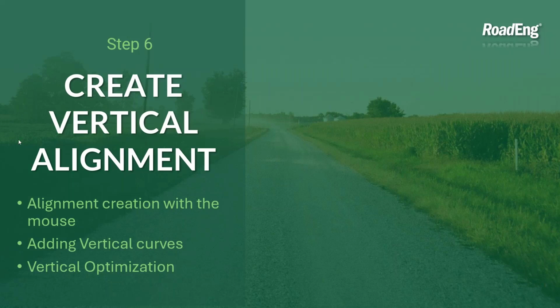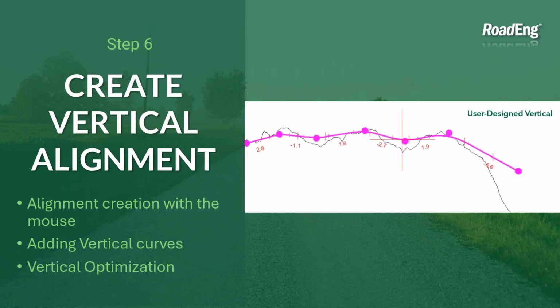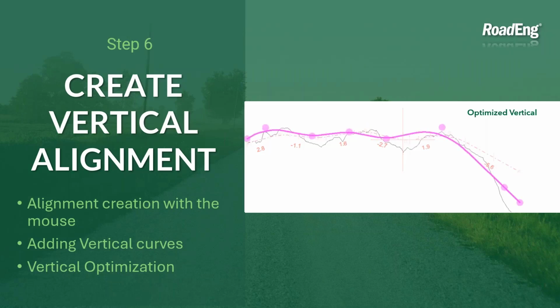So right now, if I can get this working here. There we go. Right now, the alignment that Matt's got in his, because we used polyline to alignment, it removed the profile and we're just following the ground. So to start, we can go and do that sort of manual process, designing a vertical. Then we can leverage optimization to basically move that profile in order to minimize the cuts and the fills. So yes, you can create your profile by yourself, or you can use a tool.